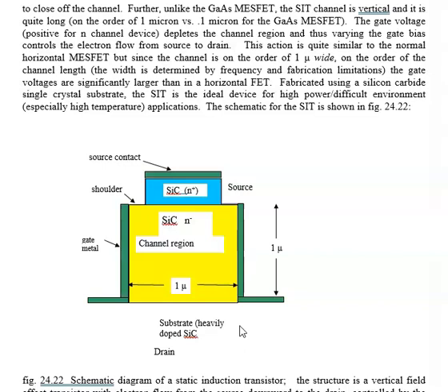It has a wide band gap, so even at 500 degrees C we're essentially intrinsic, whereas at 500 or 600 degrees C silicon starts to have a very high intrinsic concentration, and gallium arsenide can't even stand up to those kinds of temperatures. So it's very good for high temperature environments, and it's very good for high power applications.